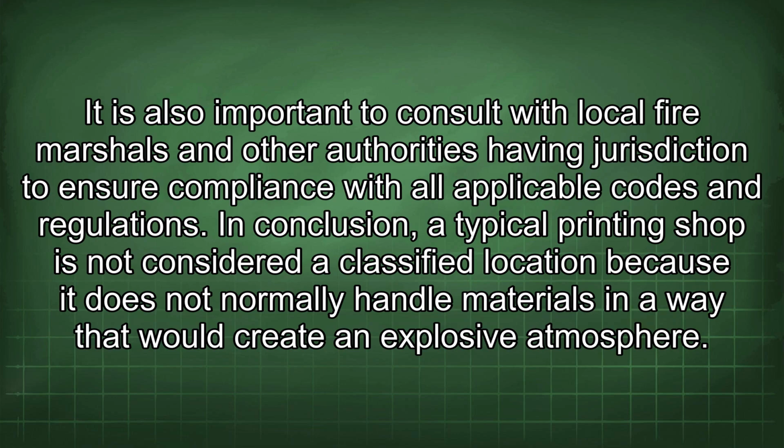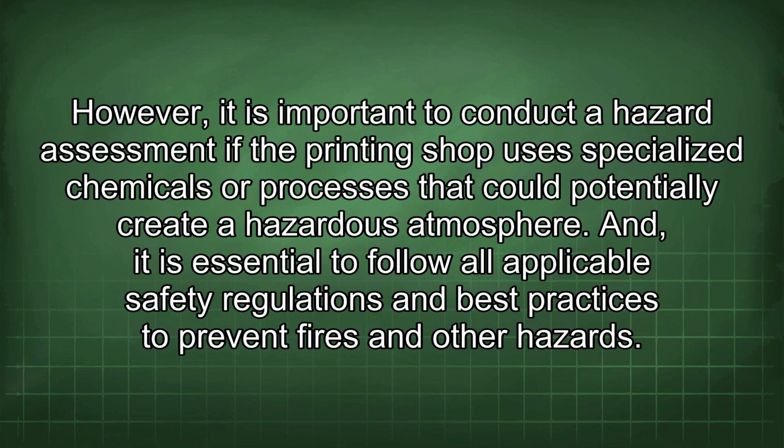In conclusion, a typical printing shop is not considered a classified location because it does not normally handle materials in a way that would create an explosive atmosphere. However, it is important to conduct a hazard assessment if the printing shop uses specialized chemicals or processes that could potentially create a hazardous atmosphere. And it is essential to follow all applicable safety regulations and best practices to prevent fires and other hazards.